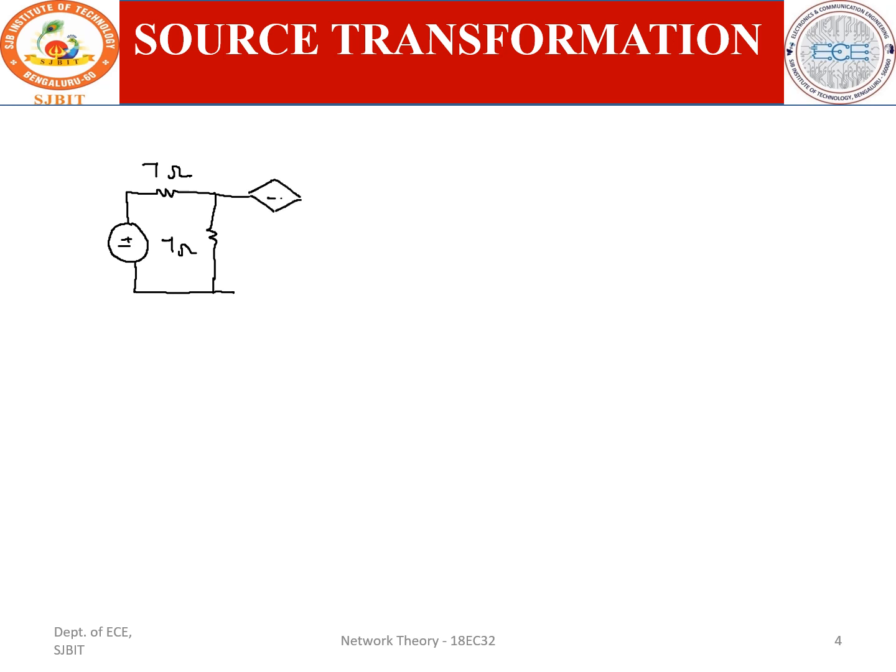This is like this. This is your minus plus, and this is a 51 Vx. 17 ohm and 9 ohm are in series, that will become 26 ohm, and 2 ohm. This is plus minus Vx. 2 ohm is also in series, but we have to find out the current flowing through the 2 ohm resistor. Therefore, you have to retain this 2 ohm resistor. And the remaining voltage source that you have to write, this is positive, negative, and is a 9 volt, and this has to connect like this.